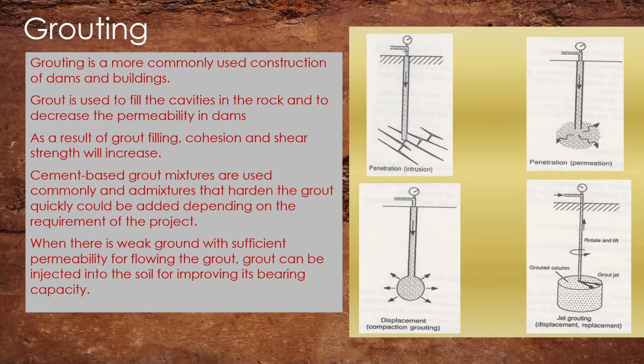Now, in dams, you generally construct the dam on very hard soil or rock. So if you have a permeable soil or permeable rock under the dam, in large dams you excavate up to the rock. Beyond that, you construct the dam. So even in the rocks, there could be cavities and cracks. All those will be there. So if you apply very high water pressure, the water will seep through these cracks. Therefore, we have to seal those. Therefore, we drill the holes and do the grouting of the rock.